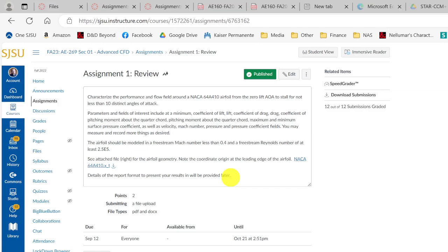No, I was wondering because the sphere and the pins I was getting convergence really quickly, but my heatsink was taking a long time. So how close together were your cylinders for your pin fins? My guess is your gap was about 5 to 10 times bigger. Yes, it was around 5 millimeters, 6 millimeters. Whereas your gap between plates was much smaller.